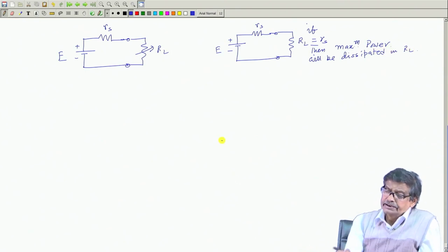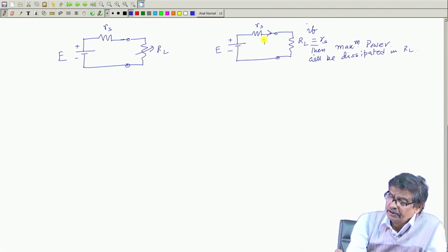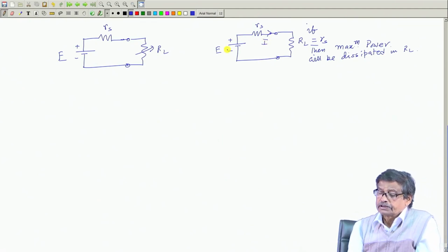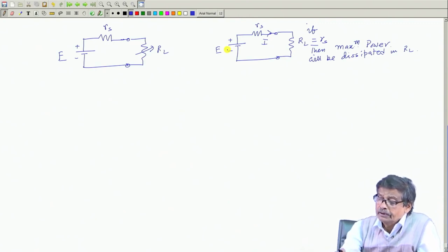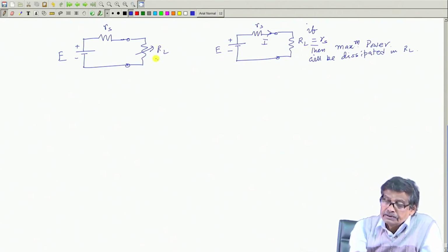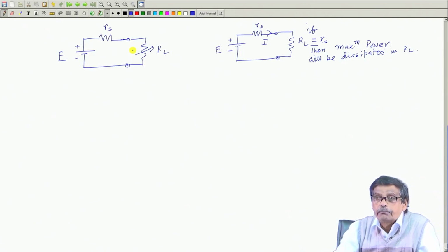And only one additional information I will tell you about this maximum power transfer theorem, that maximum power will be consumed by the load resistance when its value is equal to source resistance, that is in language people say load resistance should be equal to the source resistance in case of DC circuit for maximum power to occur in R_L. Okay, that is fine.